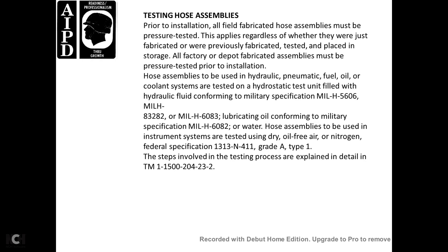Testing hose assemblies. Prior to installation, all fabricated hose assemblies must be pressure tested. This applies regardless of whether they were just fabricated, or previously fabricated, tested and placed in storage. All factory and depot fabricated assemblies must be pressure tested prior to installation. Hose assemblies for use in the hydraulic, pneumatic, fuel, oil, and coolant systems are tested on the hydraulic test unit